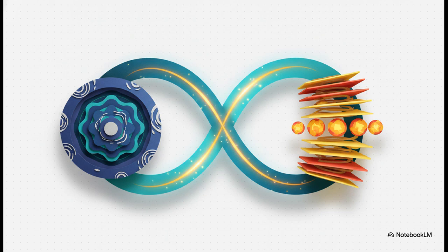Over time, in a steady state, inductors act like short circuits, happily letting constant current flow through while resisting any sudden changes. Capacitors, on the other hand, eventually act as open circuits to steady voltage, blocking constant flow, but they eagerly absorb sudden changes. One loves steady flow, the other loves to store up pressure. When you put them together, they create this beautiful push and pull dynamic, passing energy back and forth from the magnetic field of the inductor to the electric field of the capacitor.